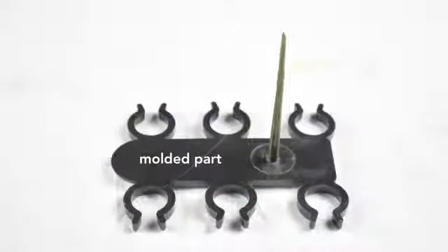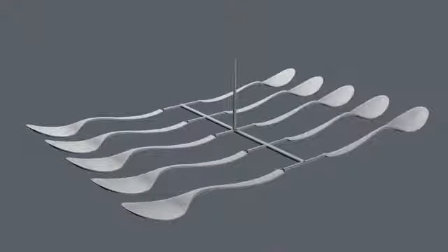When the part drops from the mold, an operator has to remove the sprue, that section of plastic that connected the injection unit to the mold. Sprues are manually twisted or cut off the part. Sprues are attached to objects only in molds that make a single part at a time, like a chair. Smaller objects are made in multiples in a single mold.